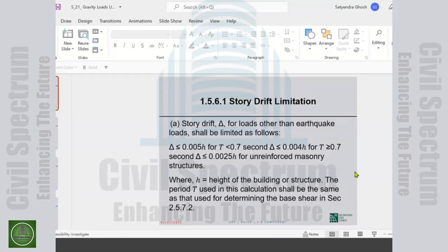We take a uniform load of 15 pounds per square foot for movable partitions, and that number is 25 pounds per square foot in BNBC. But it is a uniform load that we take, not line loads. That's much more complicated. And that's what the last line was saying in BNBC. I forget which slide. It tells you a minimum uniform load of so much.